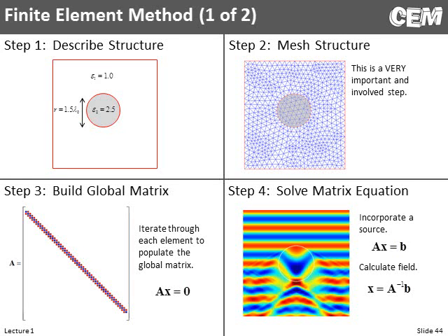If there's something abrupt happening here, we can really easily reduce the size of the triangles there to resolve that and leave the rest really coarse. It's very, very efficient at doing that. That buys you a lot of efficiency, but it also buys you a lot more headaches in the formulation and implementation that just aren't there for things like finite differences.